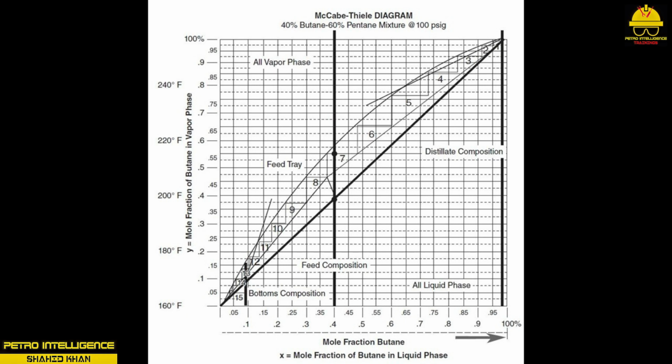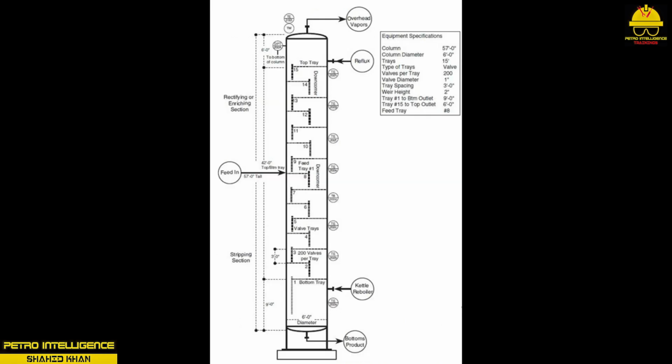In many cases, it is difficult to get a complete 100% separation of components without additional processing. Plate and packed columns used in series may provide this additional processing. When a mixture is preheated and pumped to a 10, 15, or 30 tray column, the lighter components will move up the column as vapor and the heavier liquid will move down and collect in the bottom section.